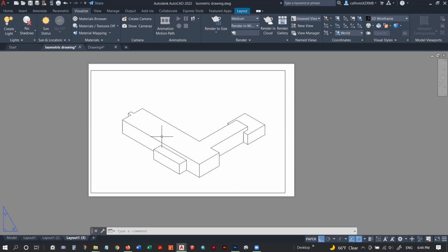So any measurement here, let's measure that same length of the building I measured in the past layout, which was 270 feet in the other one. It is now 220 feet in this one. So anything in this isometric projection is going to suffer foreshortening along all 3 axes.